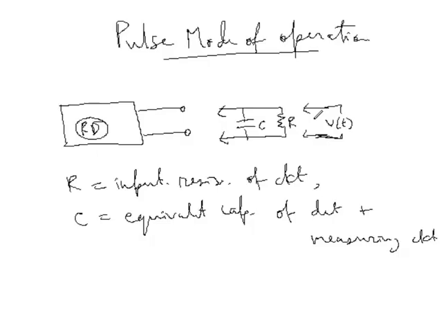Now you see what happens in most cases. The time dependent voltage Vt across the load resistance is the fundamental signal voltage on which the pulse mode of operation is based. Now, two separate extremes of operation, we will talk about them. They can be identified, and this depends on the relative value of the time constant of the measuring circuit.